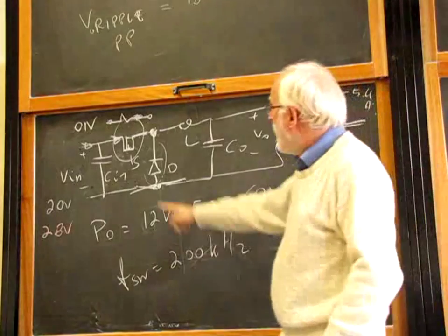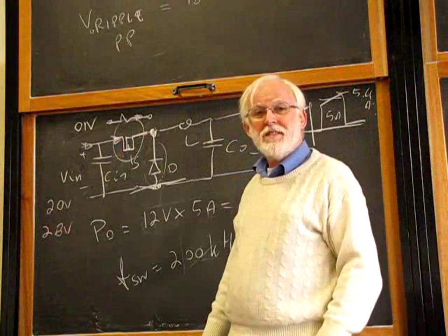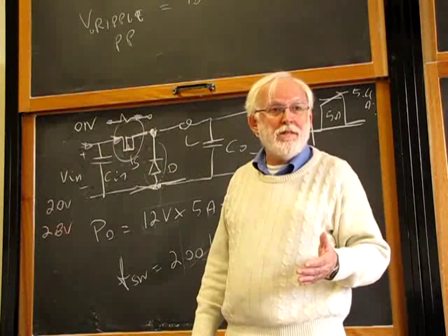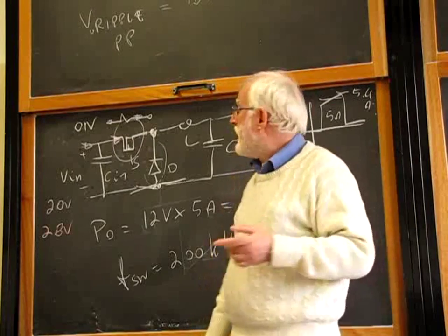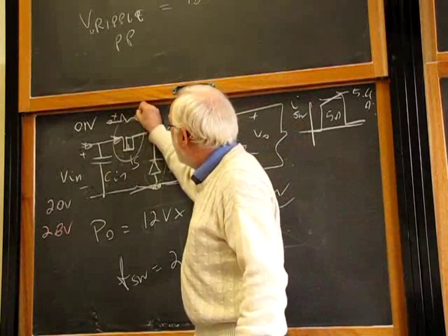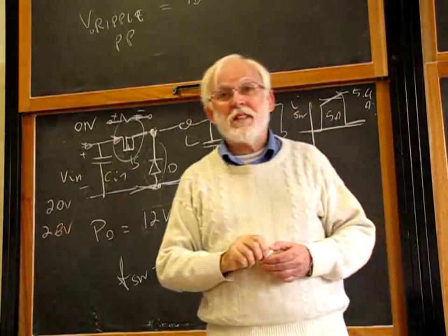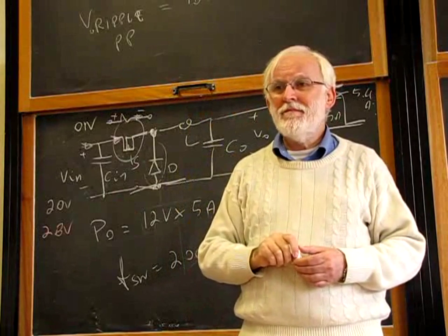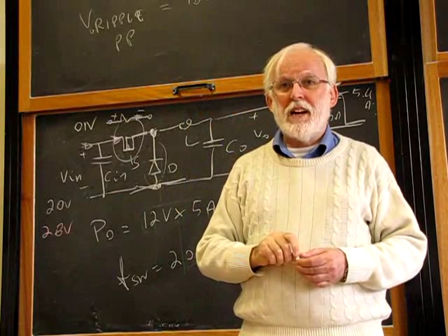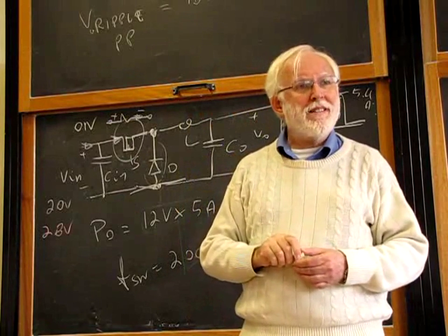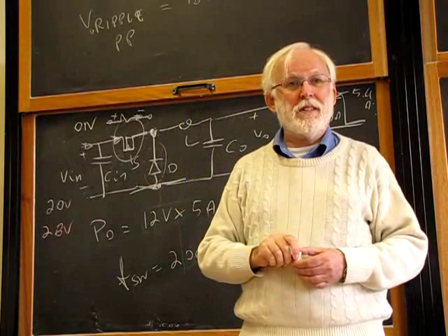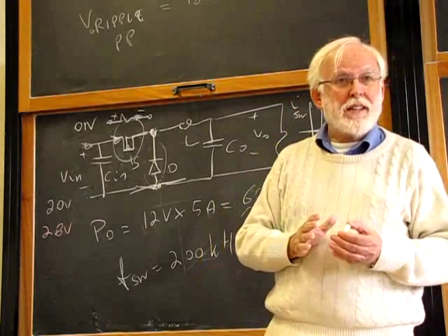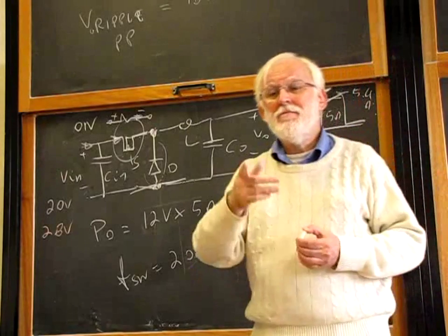What happens when you have a current flowing through a resistance? We have a voltage drop. This is the requirement. How much voltage drop are you willing to accept across this MOS transistor? Comparable to the diode voltage drop? Well, you can do better, because the diode voltage drop is half a volt. You can go lower than this, one order of magnitude lower.